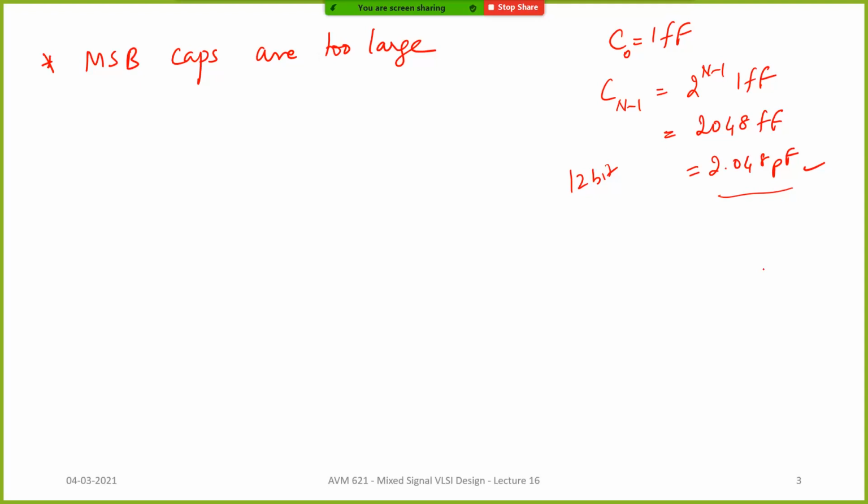And as for the other point that somebody brought up, it is the capacitor, at high frequency, it will change easily. So the impedance of a capacitor is what? Xc is 1 by j omega c, right? So as C reduces, your Xc will only increase. So what do you mean by high frequency noise?